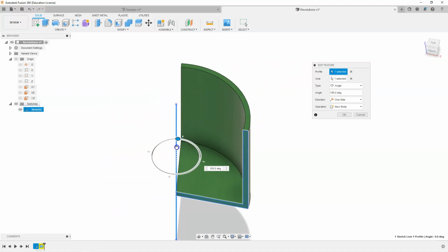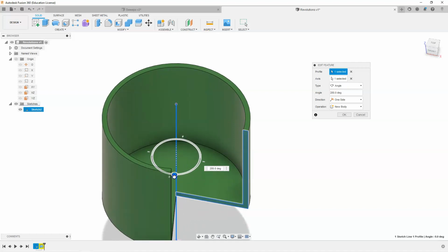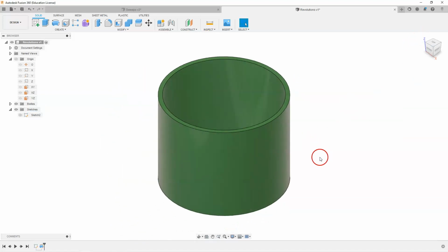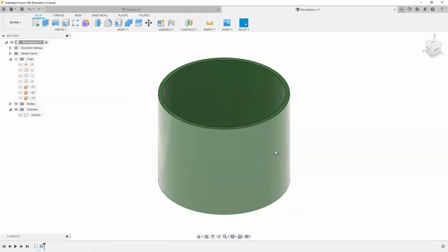Okay, so hopefully you can see how that rotation works, why our axis selection is important. And I'll finish this off at 360 degrees. Select OK, and isometrically we can see that nicely formed shape that may be a little bit quicker than adding some using extrusion or shell commands. Just going to save that feature, and we could go add our radiuses on this just using our fillet commands if we were going to go back to that cup style.